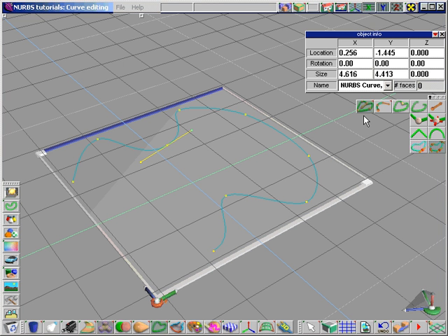By default, the Curve Edit toolbar opens with the Move Point tool selected, which allows you to left-click drag to reposition existing points in the Draw panel. Right-click drag moves the point up and down in the Z-axis off the Draw panel surface. The Draw New Curve Point tool will continue an open curve from its last placed point, and the Close Curve tool will connect open curve endpoints.